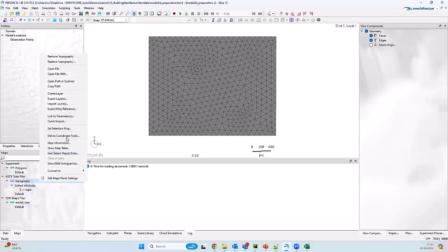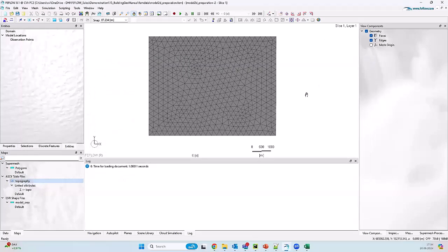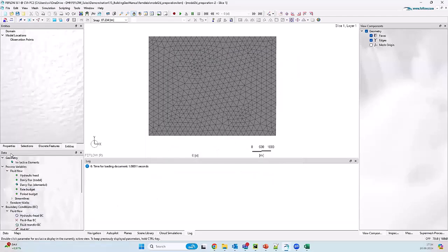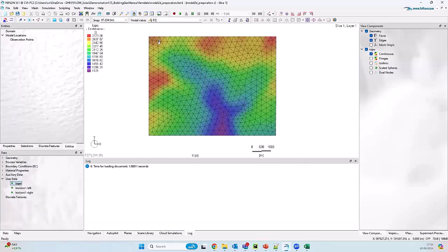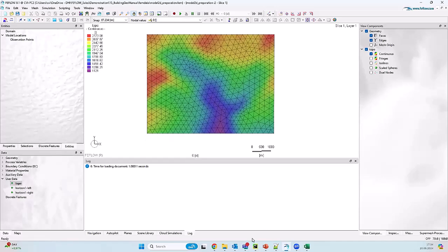And then I have a set of points. As I was mentioning, these points consist of X, Y, Z. So do you want to create your domains for the simulation? What I will basically do is pass this information to, for example, a nodal distribution that I create, topo interpolates, and then FEFLOW will give you this distribution here. So this will be my topographical surface. On this, with the 2D mesh, I will be able to create a bounding box for the 3D supermesh.